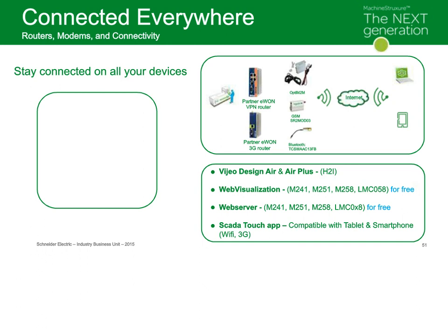Web visualizations. These are HTML5 web pages embedded within the controller's web server that are user configurable. So you can pull in a toggle switch, for instance, and all you have to do is change what variable it is actually actuating when you change it on your iPad. I mentioned HTML5 web pages. The HTML5 encoder is actually embedded within SoMachine software, so you don't actually have to know how to program a web page. I don't know how to do it. Maybe all you guys do, but I'm betting that some of you don't. So you're not going to be held up with that capability.